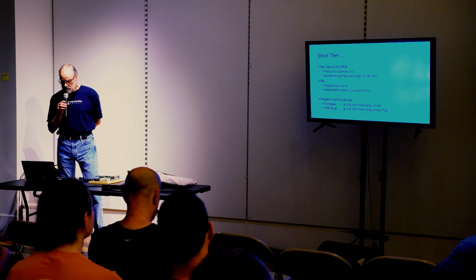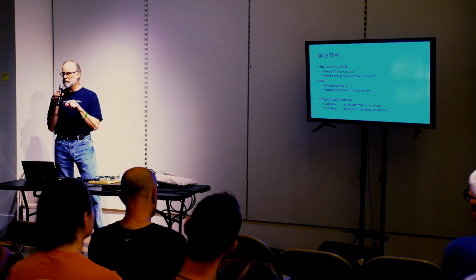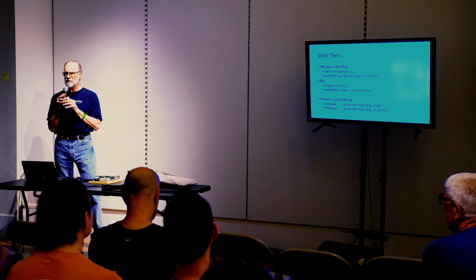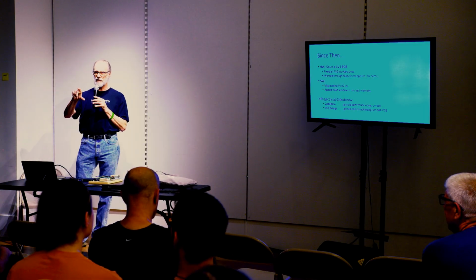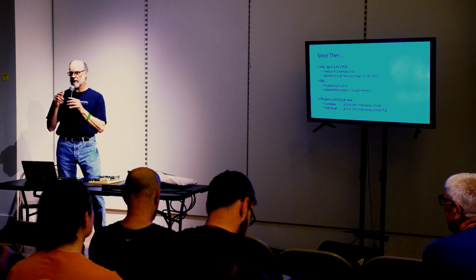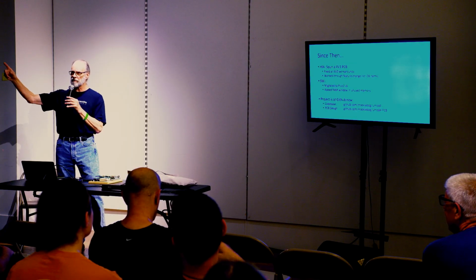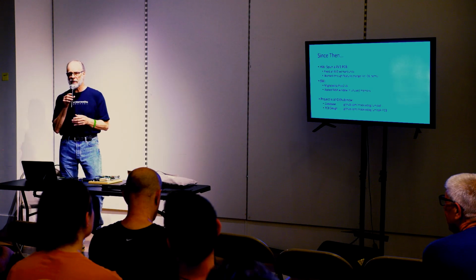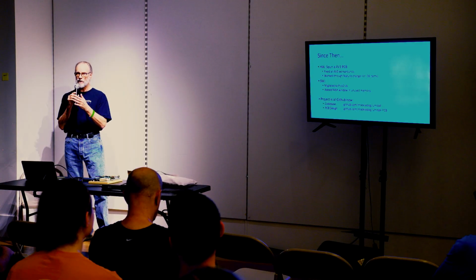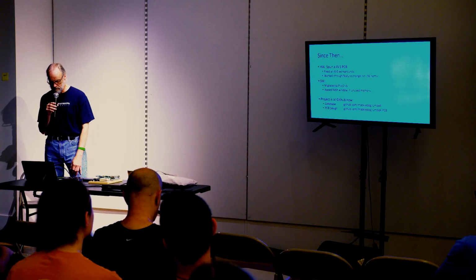Another thing I did was I actually turned part of the EPROM into RAM. So it was not a difficult software issue, but what that let me do was to take the HC11 stack, and their code base had a fair bit of stack paranoia in it. So I took the stack and relocated it into my new RAM window inside the EPROM. And that totally gets rid of all that. There is no possibility of a stack collision anymore because it just lives completely far away from everything else.